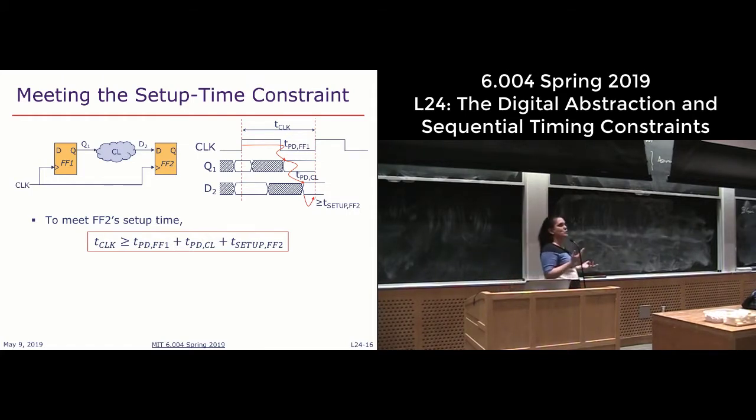So we had a notion of this, and we've been talking about trying to minimize our clock period, but the piece that we hadn't really taken into account is that aside from the propagation delays of your various components, there's also this additional piece, which is the setup time that you must satisfy in order for your registers to work properly.